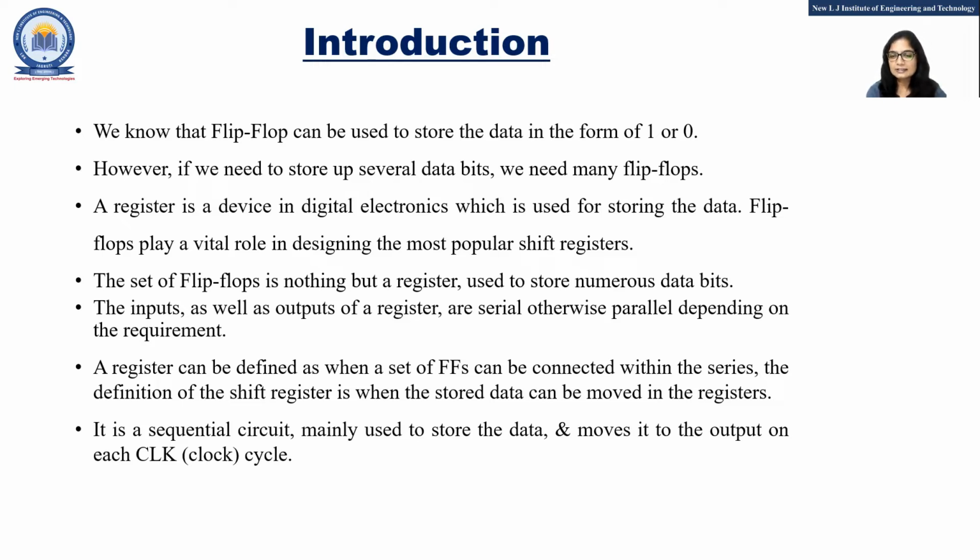A shift register is nothing but a simple register which will shift the data right side or left side. Simply, it will shift the data. So shift registers are nothing but simple registers, and a register contains different flip-flops. Suppose I am going to use a 4-bit register, then in that register we are using 4 flip-flops. Means the number of flip-flops is equal to the number of bits used in the register structure.